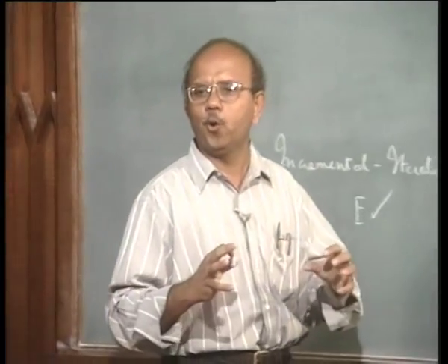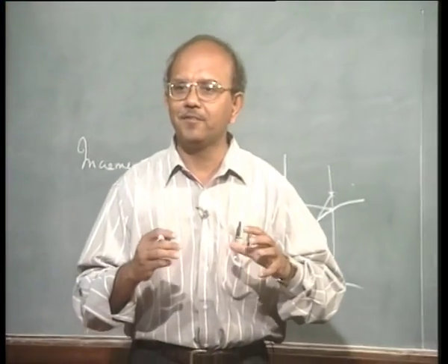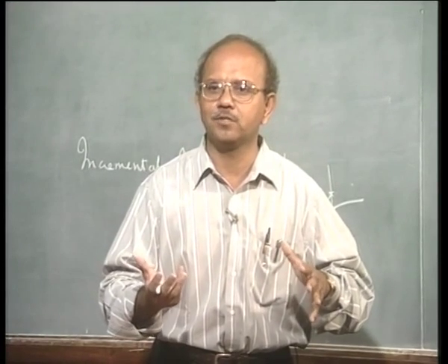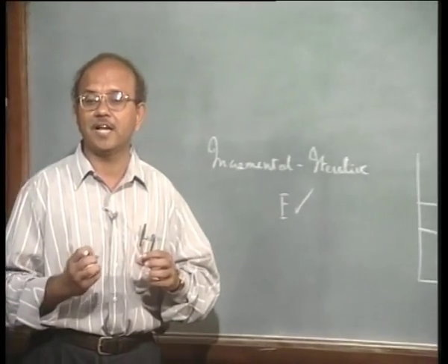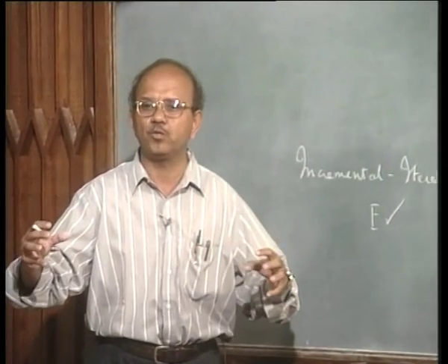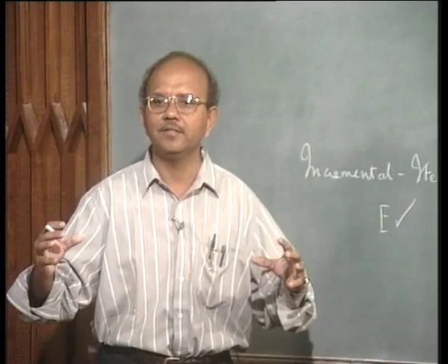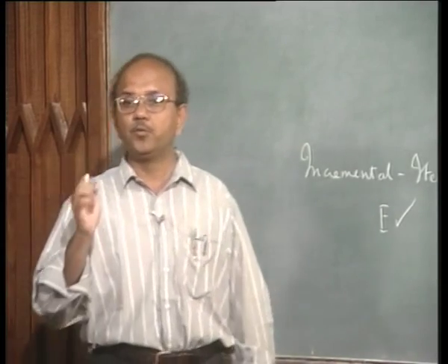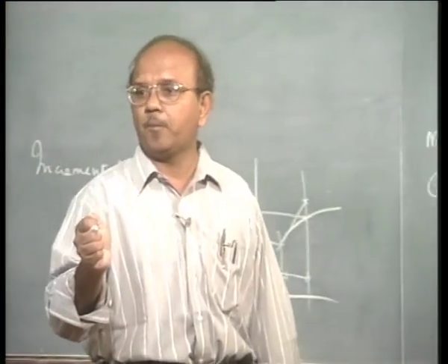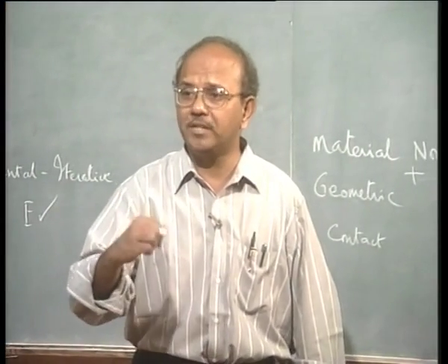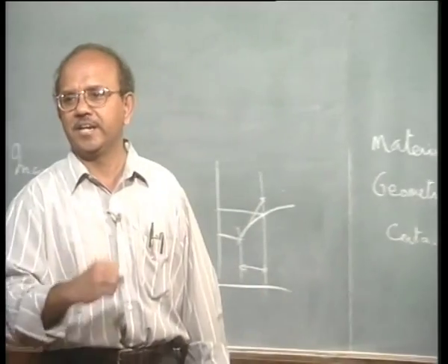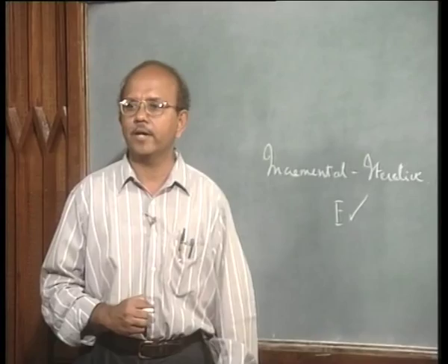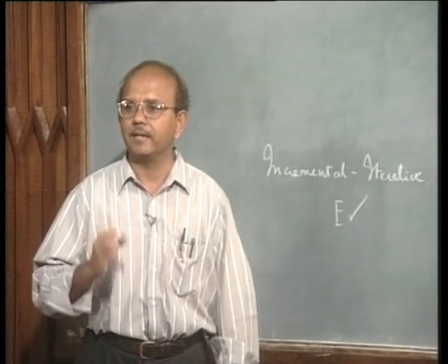What's happening when you apply the load? There will be an internal force that is created. Okay, the stresses are the internal forces. These internal forces have to equilibrate the external forces. Is that clear? So the error is the difference between the external applied force and the subsequent internal force that is generated. Okay, so that is the error.